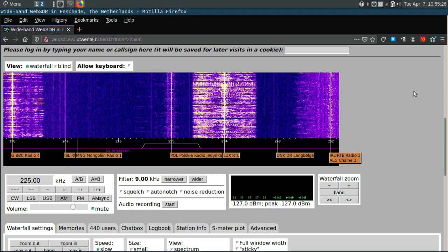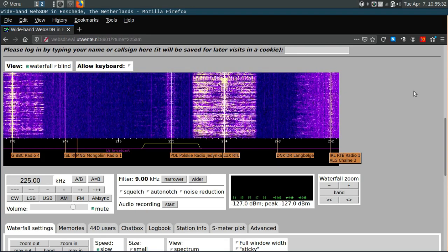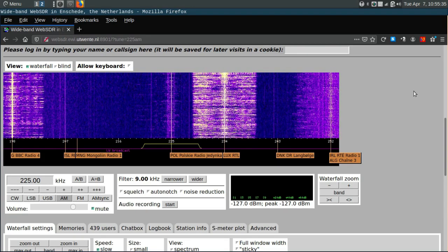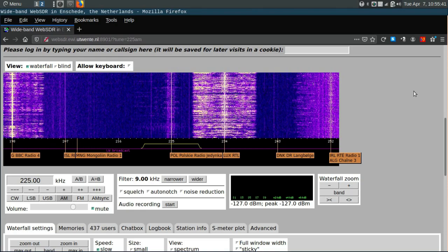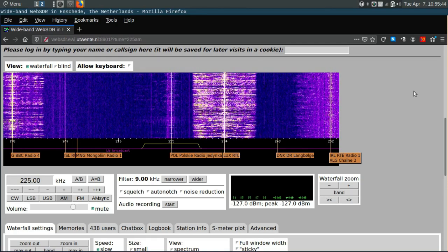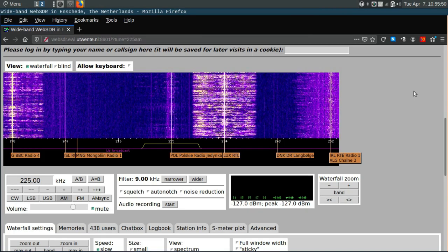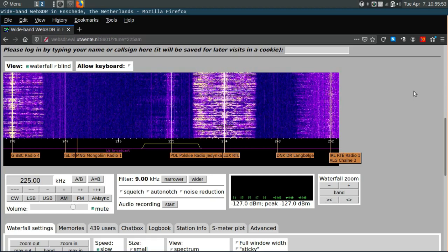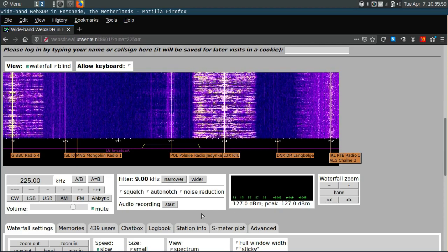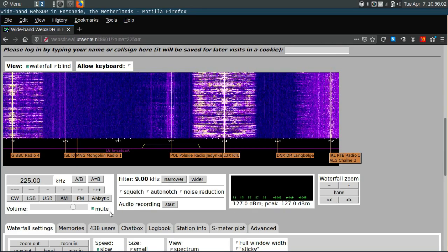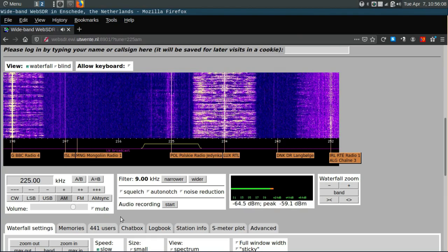The receiver is currently tuned to longwave, frequency 225 kHz. On that frequency, there is a weak signal from Poland. The mode is AM, and that signal is subject to adjacent channel interference, carriers, and plenty of random background noise. We're going to work with the filter pass bands, software noise reduction, and change the detector type, all in an attempt to make that signal pleasantly readable. First, we'll unmute the receiver. Listen to all of that noise and racket.